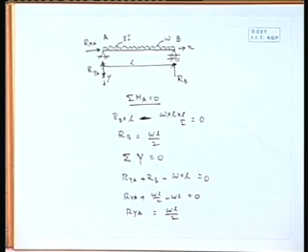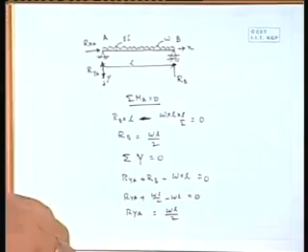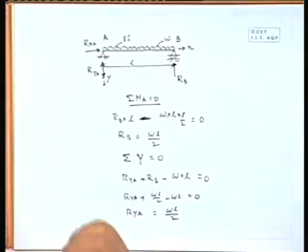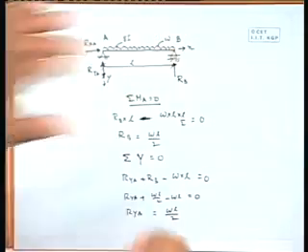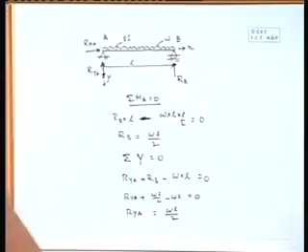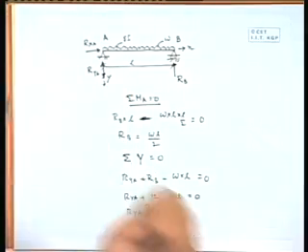So, this is a verification. From this experience, later on we can do one thing. There are some problems where we can find the answer physically and need not go for the calculation. So, straight away we will write omega L by 2, omega L by 2, because it is a quite symmetrical structure, fully loaded uniformly. So, it will be distributed halfway: omega L by 2, omega L by 2.